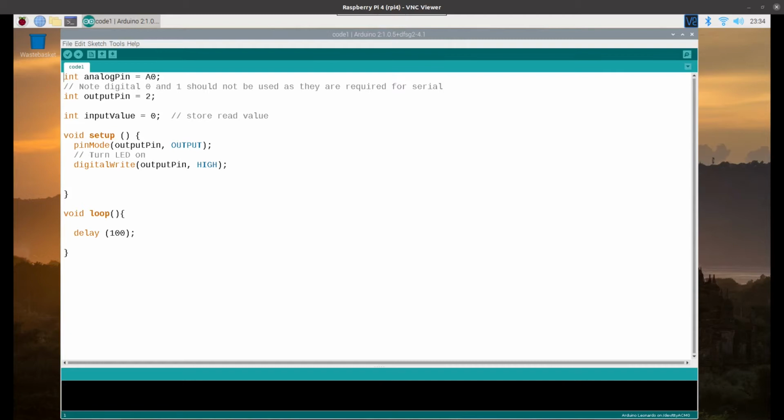First, I'll add the code which allows the serial port on the Arduino to send messages to the Raspberry Pi. Then I'll add the code that works in the opposite direction. One of the things that I'm doing here is to make sure all the messages that are sent are in human readable form. It doesn't need this if it's just communicating with a computer, and would make for more compact messages if this was sent as binary data. It's going to be much easier to understand and will help us to test using a serial console before we move on to using the Raspberry Pi to send the messages to the Arduino.